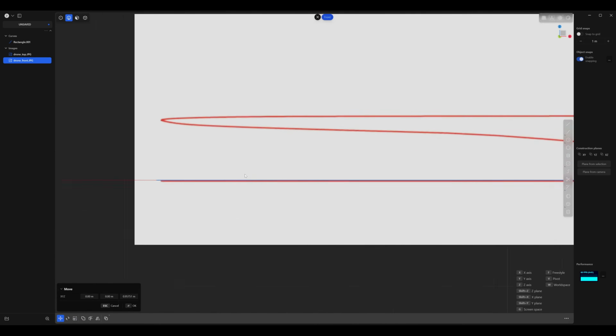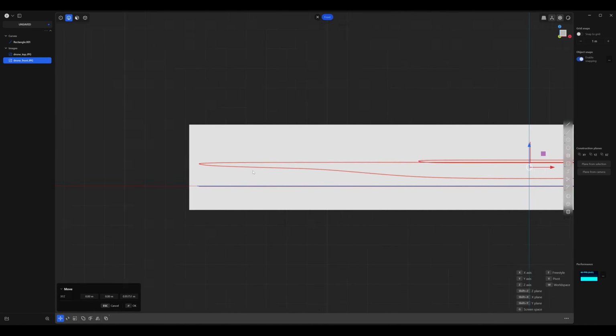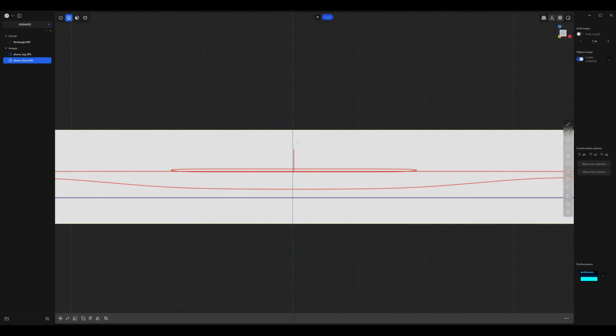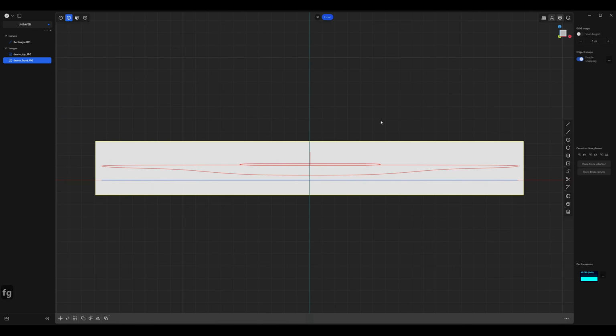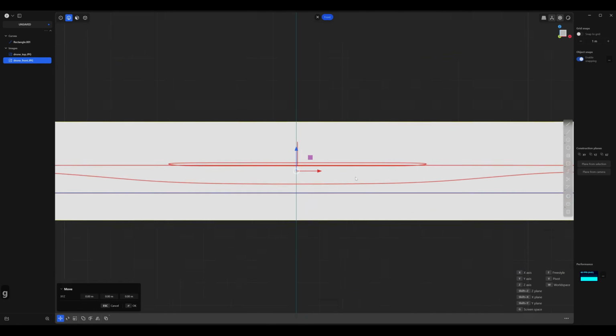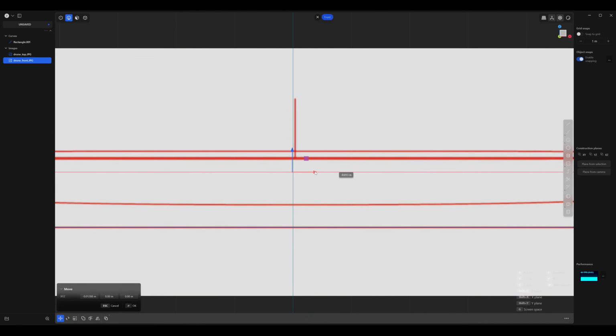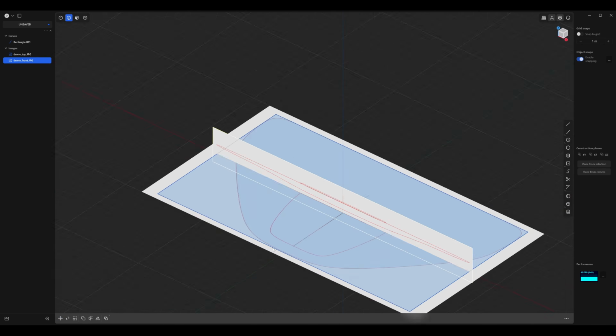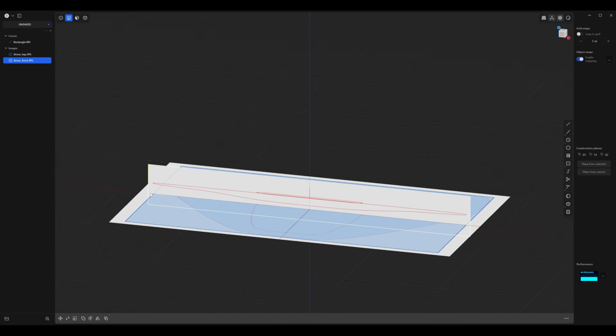So you can see that we can still move it a little bit more. I'm going to hold Shift, S twice, and hold Shift so we have a smaller increment, and press OK. And you can see it's not aligned in the center, so let's just press G one more time. And let's move it on the x-axis until that's centered. Great. So now they look like they're pretty much the same size.